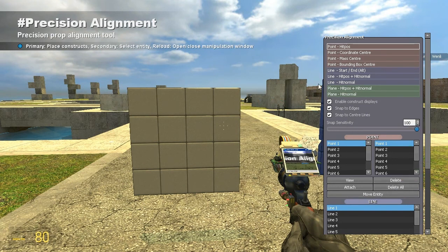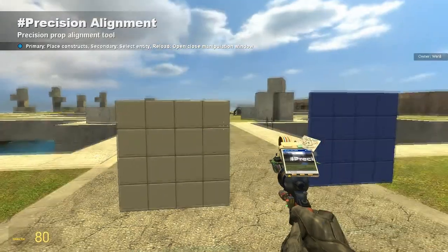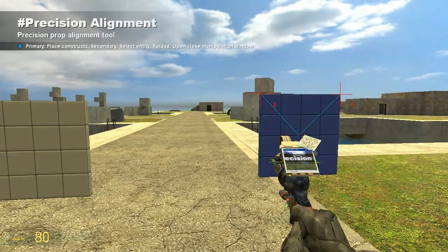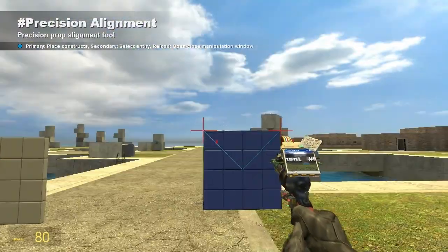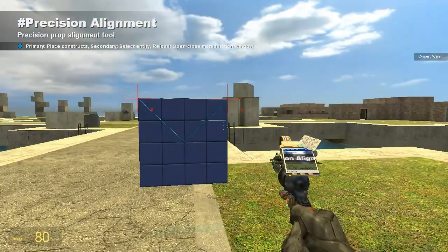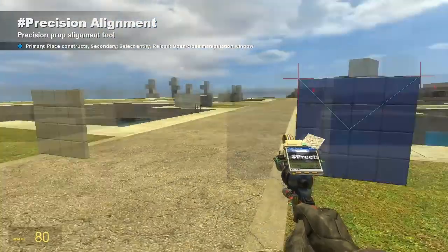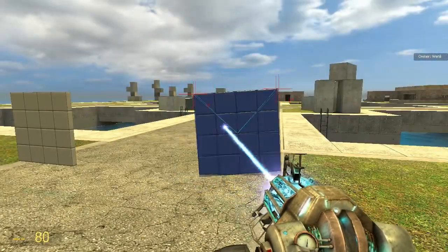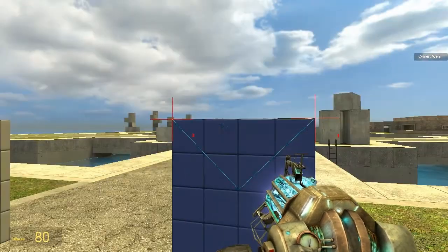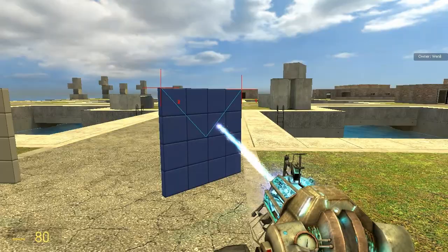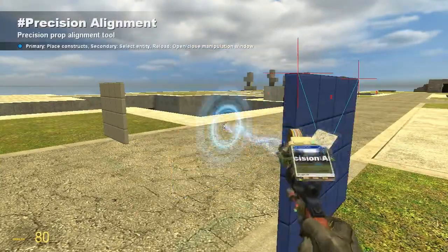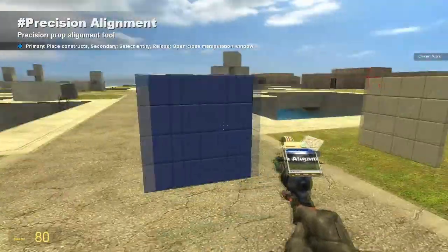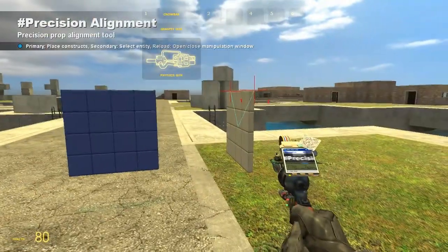The next shortcut I want to show you is pretty interesting. It's nothing new. I'll just move this plate again. And if I want to repeat the last thing that I've done, so the last thing I did was move that plate, I simply hold down Shift and right click on the plate. And that'll move it again. And it doesn't matter which direction I have this in, it always moves. Rather than taking these points into account, it simply takes the last movement into account. So I can still rotate this, and then if I shift click on it, it'll move in the same direction it moved before. And I can do the same on other props, so I can shift click on this, shift right click, and it'll move in the same direction. So that's the third shortcut I want to show you.